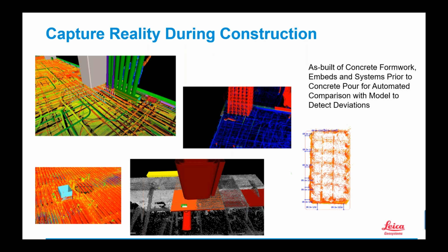So, during construction, keeping the contractor honest, I guess, is a word we could use. Making sure that they're putting it in where they're supposed to be putting it. Documenting what's there. That way, if I have to go back and do a core drill a year or two from now, I know exactly where all that conduit, all that rebar, existing parts are in that slab.